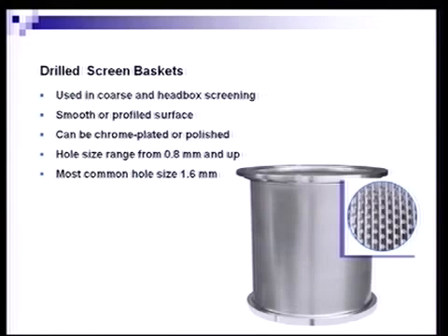That is the flake content that comes to the screen from the pulper. Specifically, a continuous pulping loop will have a fairly high flake content, for instance for packaging grades. Coarse screens are required to be operated ahead of slotted screens or fine screens because the coarse screens will remove the flakes much more effectively.